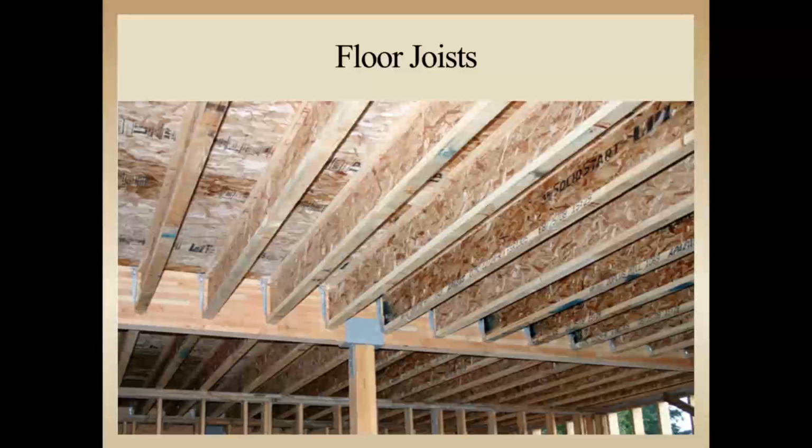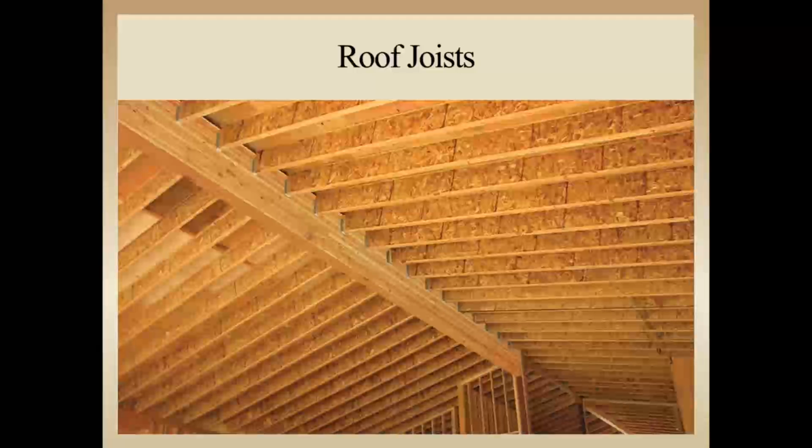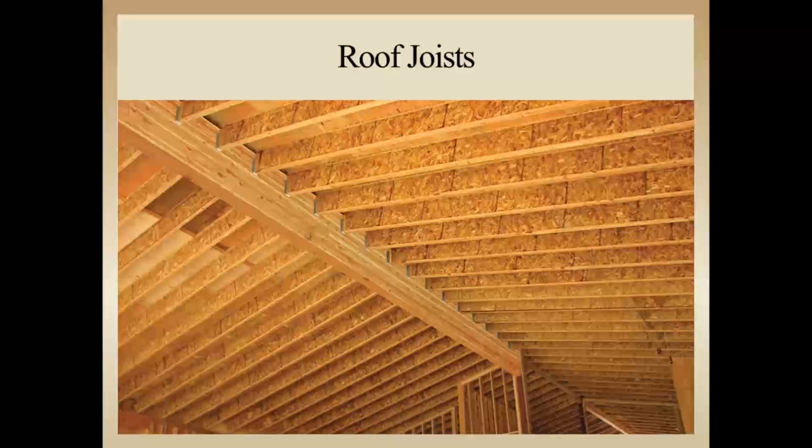In this photo, we once again see I-joists used as repetitive members being supported by lightweight metal hangers on the side of the engineered wood beam at the ridge and the exterior walls. In this application, the I-joists are being used in a simple span or single span condition. In this case, the I-joists are being used as cathedral ceiling joists on a gable-type roof and will be supporting both the roof and ceiling loads.